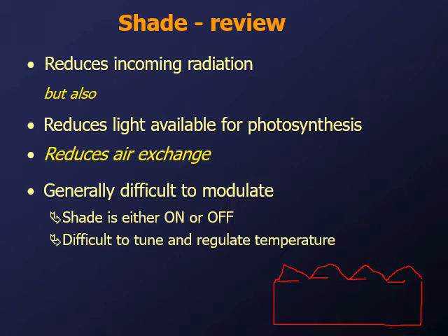It doesn't always work out like that. But the bonus is that if your vents are open, air can escape through the gap that's not closed, right? That's beneficial. One of the downsides is that more often than not, where the sun is not blocked, you get intense rays of sun coming through, and you can often burn stripes across your crop.